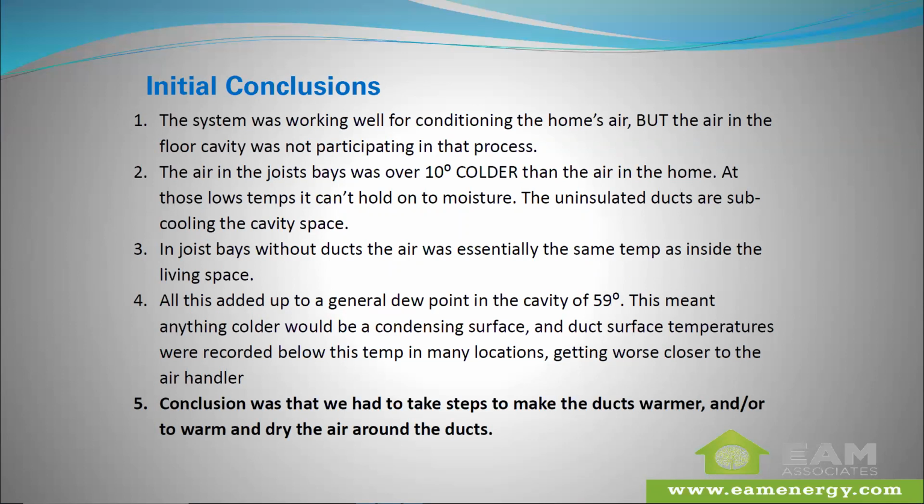On the flip side of that, though, we were finding that temperature probes put up into joist bays without ducts were really at the same temperature as the rest of the living space. So it was clear to us what the issue was there. The dew point in the cavity we calculated from all of our readings was about 59 degrees, so anything colder than that was going to be a condensing surface. And like I said, we were recording duct surface temperatures of 53 degrees all over the place. So it's just really physics at that point.